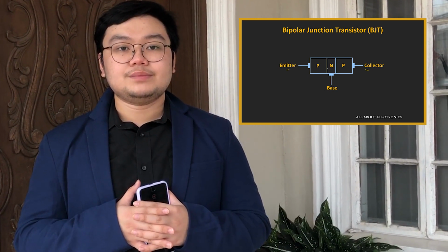Basically, the capacitor will first store energy from the circuit. The voltage will then be distributed into the resistor and to the base junction of the NPN power bipolar transistor with the model TIP41. This transistor will act as an amplifier by raising the strength of the weak signal, resulting in a strong signal that will pass through to the speaker, which results in amplification.